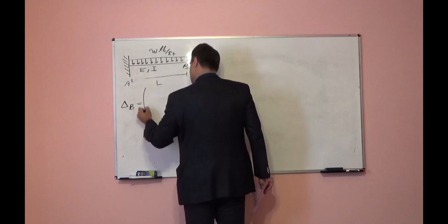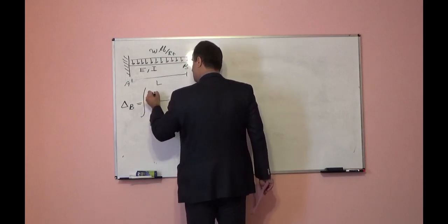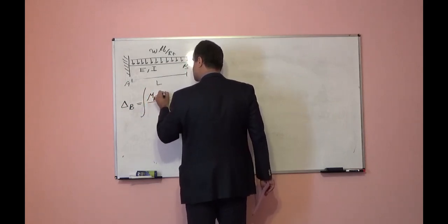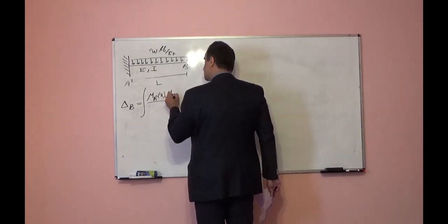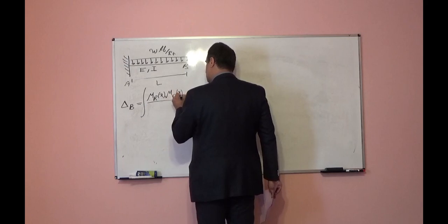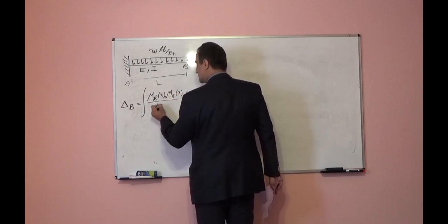Again, the formula: m_r(x), the moment because of the real load, times the moment because of the virtual load, times dx over EI.